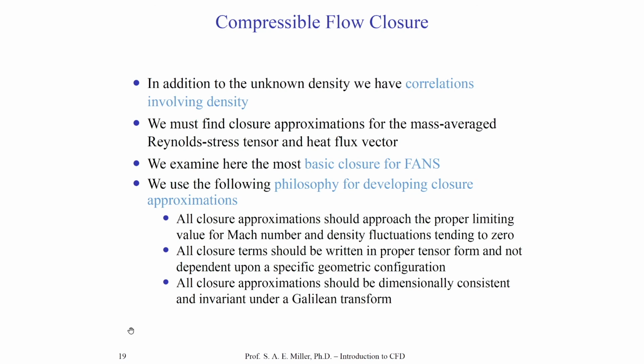We will view all closure approximations should approach the proper limiting value for Mach number and density fluctuations tending to 0. So that is, as Mach number decreases and density fluctuations decrease towards the mean value, we should actually recover the incompressible type result and solutions.